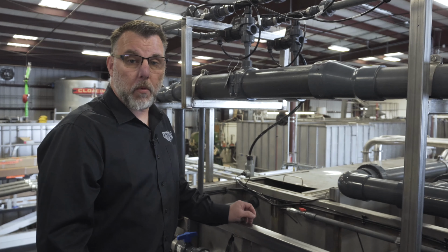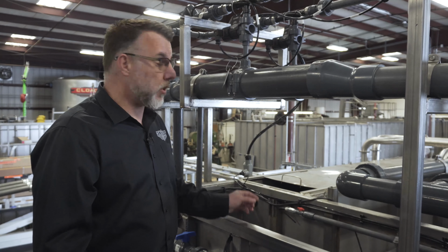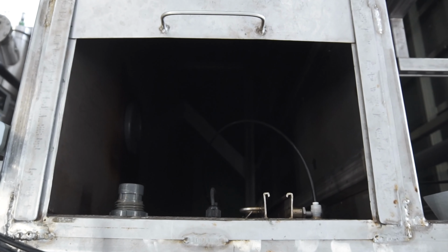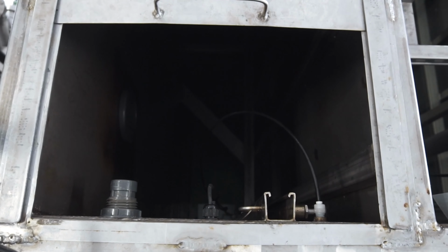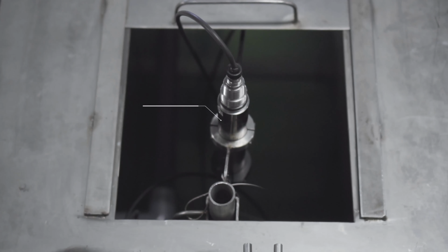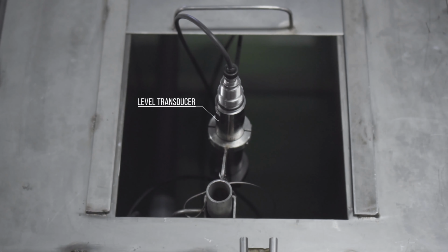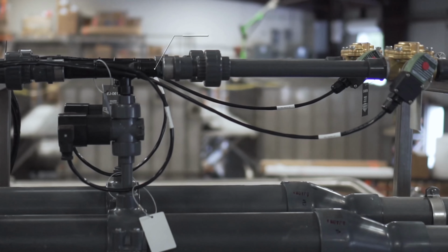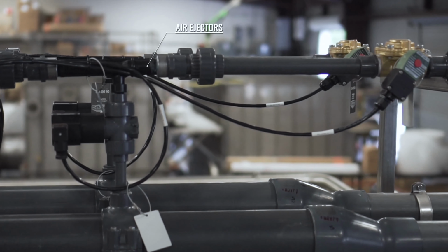Prior to disposal, membrane permeate first enters the integrated clear well. The clear well is sized to have sufficient volume to perform a clean in place on each cassette in succession. This prevents the need to utilize potable water for cleaning. The membrane process also includes level transducers in each membrane cassette and independent air relief valves to ensure no air is in the permeate line.